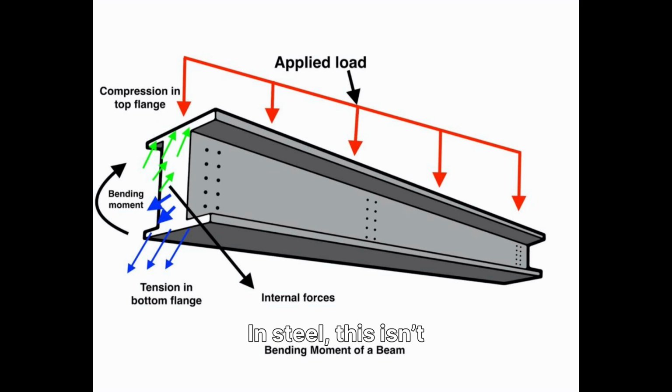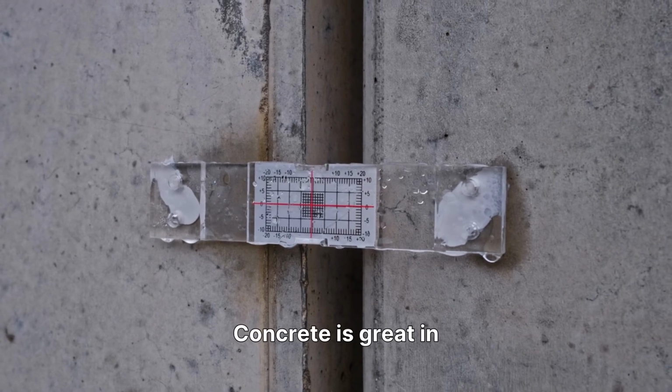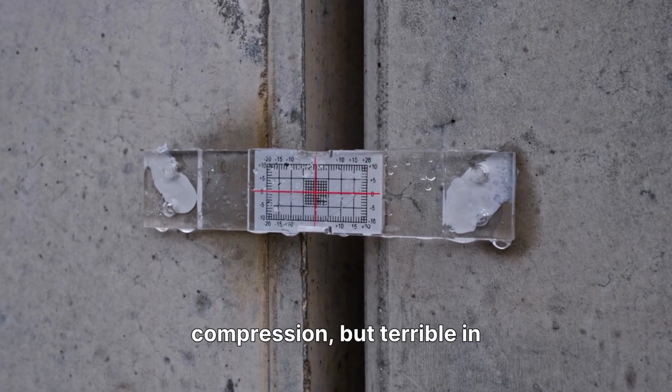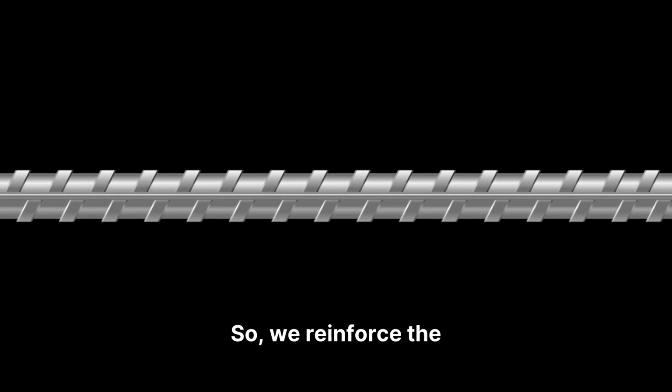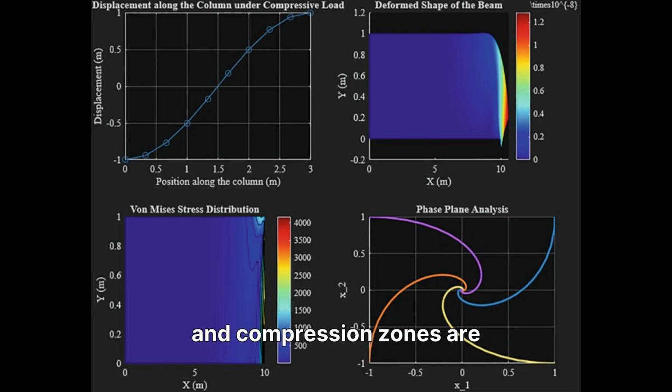In steel, this isn't a big issue. It can handle both tension and compression. But in concrete, it's crucial. Concrete is great in compression, but terrible in tension. So we reinforce the tension side with steel bars to prevent cracking. In post-tension slabs, we even place tendons near that tension face. They pull it tight, keeping the concrete compressed and safe from cracks. Understanding where the tension and compression zones are helps us make every beam lighter, stronger, and more efficient.